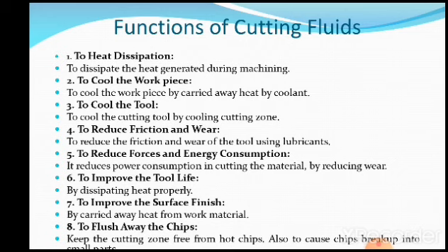To cool the tool, to cool the cutting tool by cooling the cutting zone. The continuous flow of the cutting fluids also keeps the tool from getting more heated. To reduce friction and wear, definitely it is also going to reduce the friction and wear of the tool using lubricants. To reduce forces and energy consumption, it reduces the power consumption in cutting the material by reducing the wear, because as we are going to use the cutting fluid, definitely there is a reduction of heat and thereby it is going to reduce the wear also.